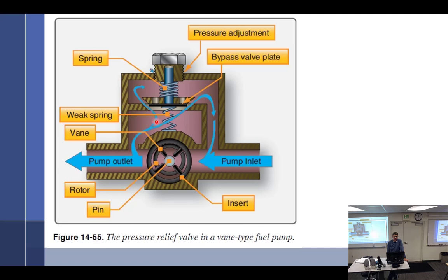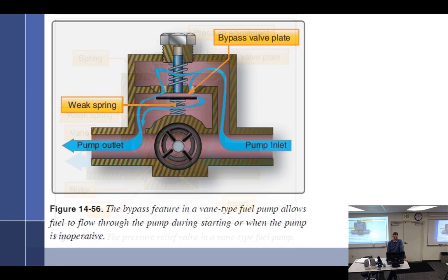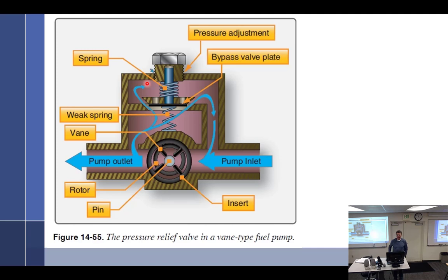But this is kind of the pressure sensing port right here. So remember that little plate that was down here? That was barely hanging out? The pressure from the pump throws it up and slams it into the top of this thing. It ain't coming down now because the pump's holding it up. All that pressure here is holding it up. All the pressure here is going to push it and hold it up. Then it's going to take this piece right here and turn it into a pressure sensing unit, pressure bypass.